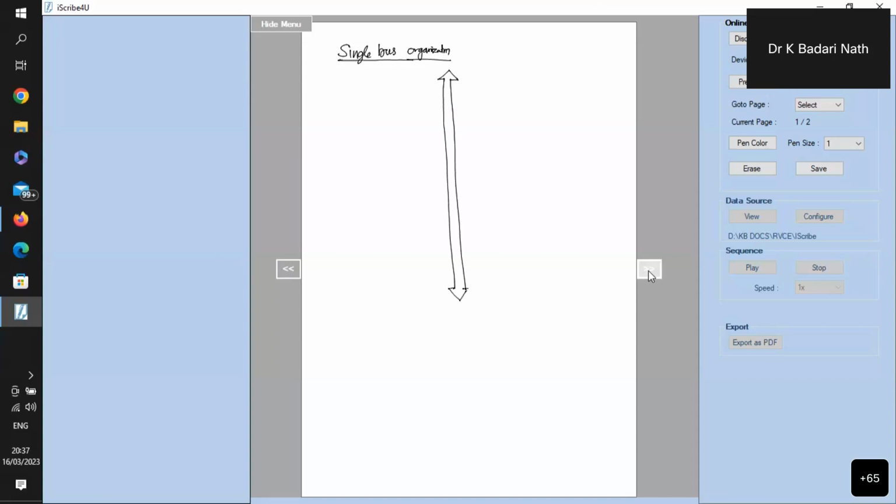So this is the internal bus. The size of the internal bus is always the size of the word length. If the processor is 32-bit, the size of the internal bus is also 32-bit. Now, the first block present inside the processor is the program counter. The program counter is bidirectional. That means that when you execute an instruction such as branch greater than 0, the program counter can be written also. Otherwise, the program counter contents will always be brought out through the MAR for generating the address where I have to fetch an instruction.